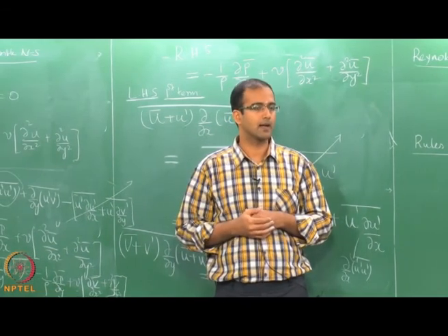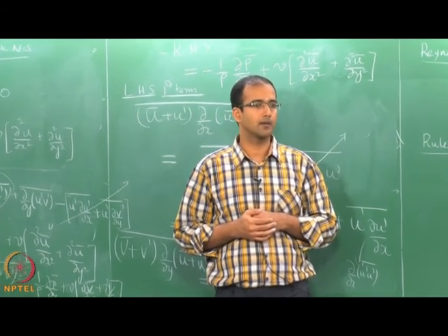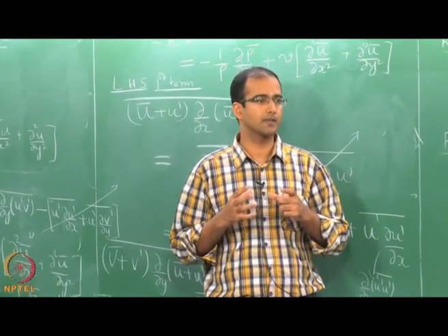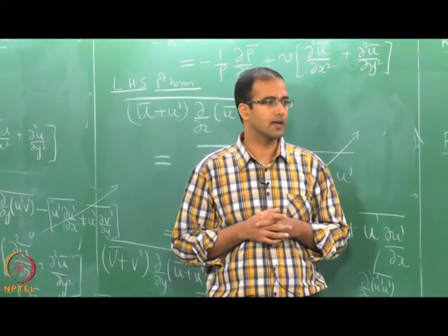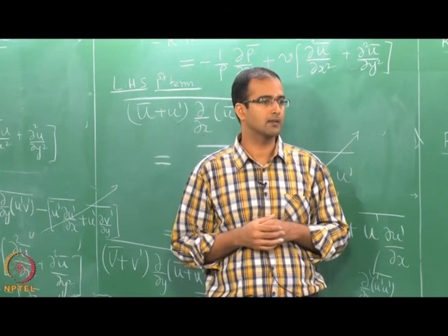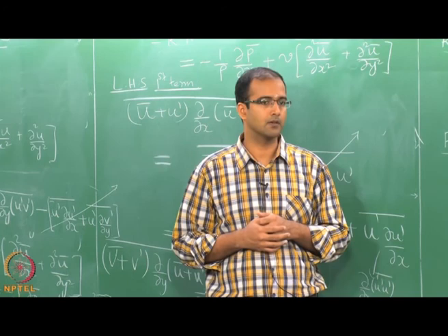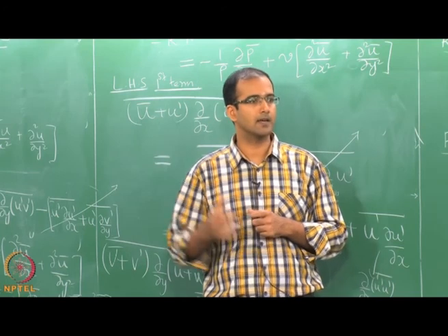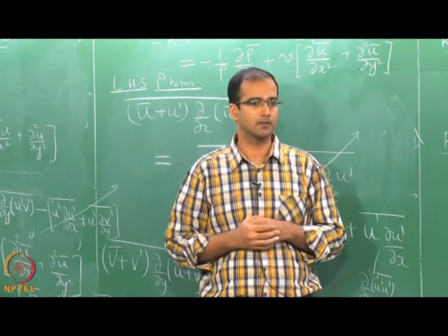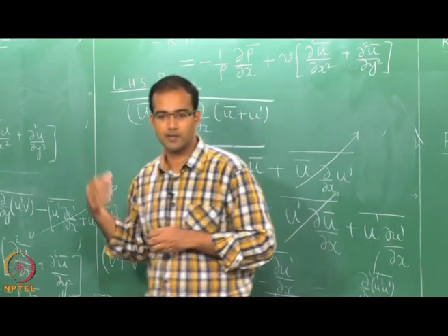They are not stresses in the conventional sense, which impede the flow. They are the ones which actually promote the exchange of momentum and energy. Therefore they have a negative sign because they originate from the inertial terms. So, these are called turbulent stresses.